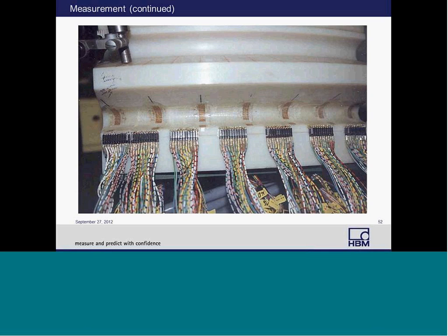So here's an example. We have a good soldering technique. We have a gear wheel here, and we have a variety of different strain gauges mounted on the gear wheel. And the wiring is placed such that it's protected from the live test and is able to make measurements over dozens of channels.